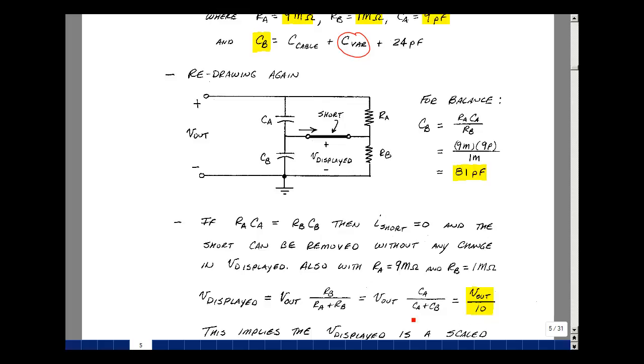Now the disadvantage of the probe is that we're making the signal smaller, and so if we're measuring a tiny voltage, we're making it even smaller, and we eventually get buried into the noise of the oscilloscope. What we've effectively done is change the effective impedance looking back from our circuit. So we'll take a look at calculating that on the next page.